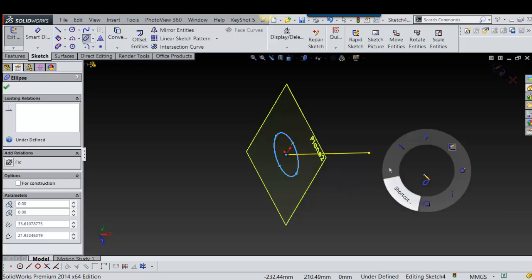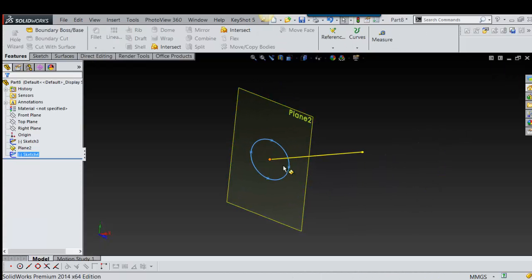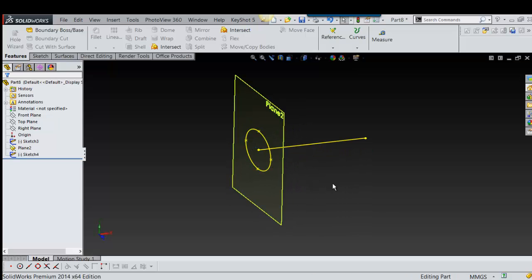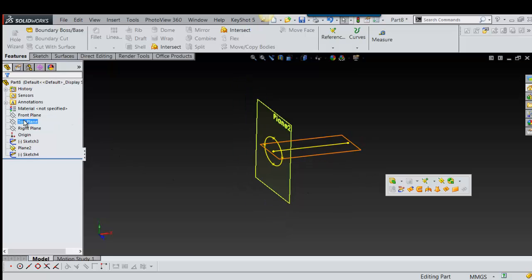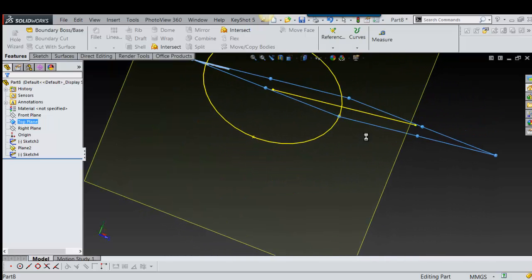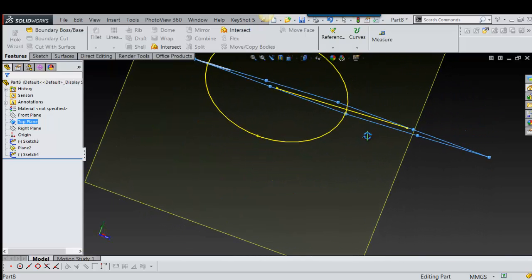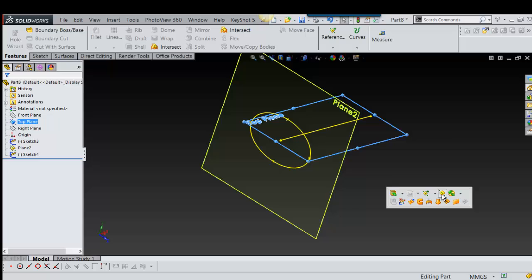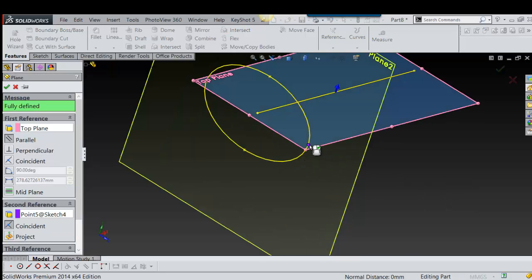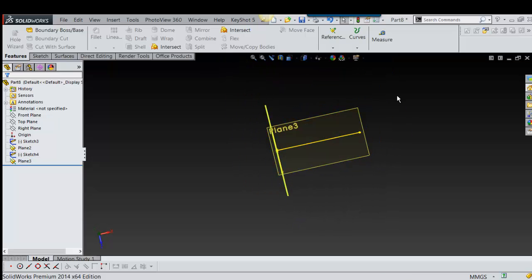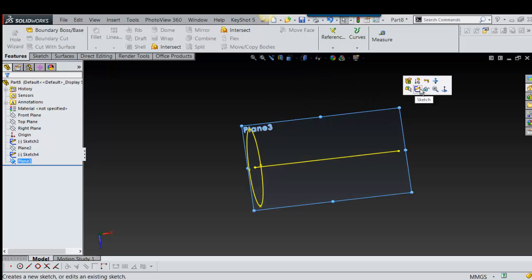So on the guide curves, you have to have a plane that goes either across this way or across this way. So we're going to put one on this point. So I'm going to select this plane. See, it happens to work out that this one's pretty close. It actually is right. So we'll go with that one. Just to be sure, I'm just going to take my plane and select that and say OK. So now I know it's on there. And next I could do is hide this to get out of my way, and sketch on that.